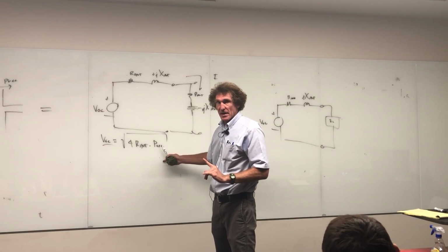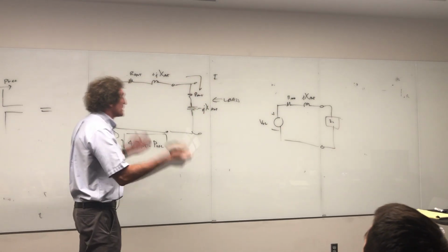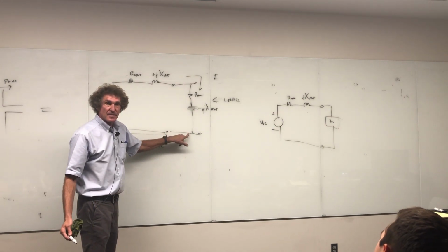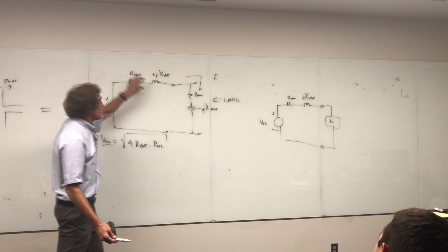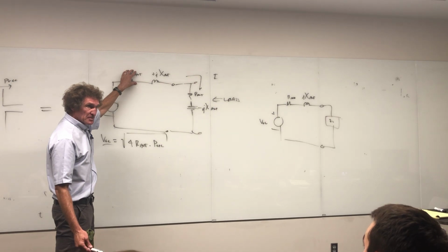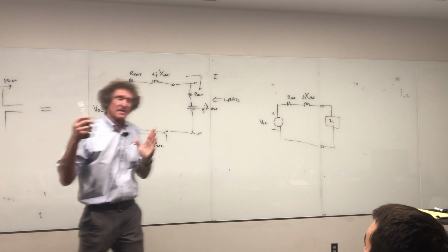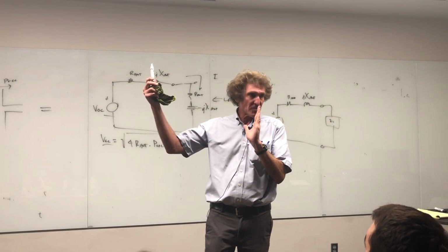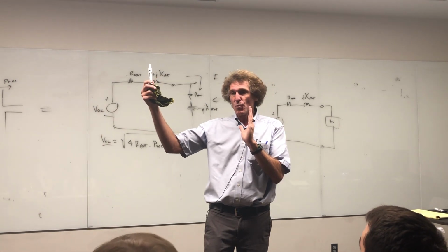Now something else I'm going to tell you. It's not brought out in the book. If you think about this, because under the ideal circumstances, this is an external load to the antenna. The most power we can actually dissipate would be half of the total power. Do you all see this? This R antenna right there, that's part of the internal resistance, the radiation resistance of the antenna. When that antenna actually receives power, it is still going to re-radiate, or there'll be power reflected off of that. And that has to do with the radar cross section of the antenna. And there's more on that later.